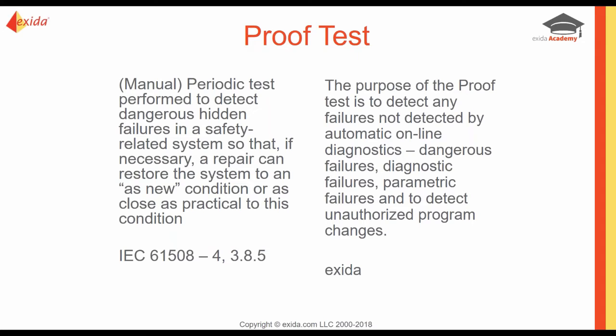And it makes sense why you don't want to detect the failures already found by automatic diagnostics. If you're already running those diagnostics all the time, they're going to find so many failures, but that proof test needs to find the ones that the automatic diagnostics won't. If you're already checking for certain failures, don't waste your time and don't waste your money rechecking those portions of the dangerous failures.